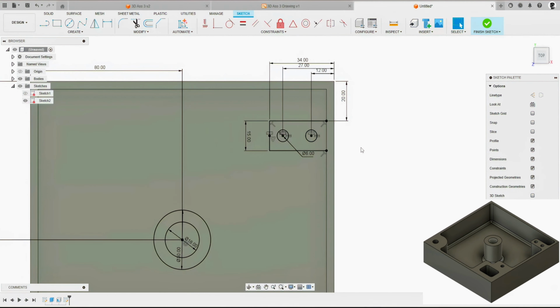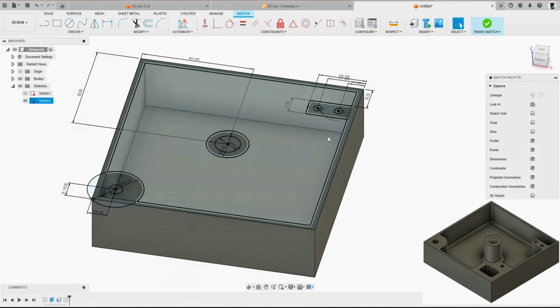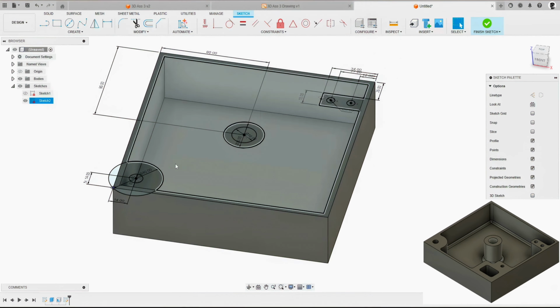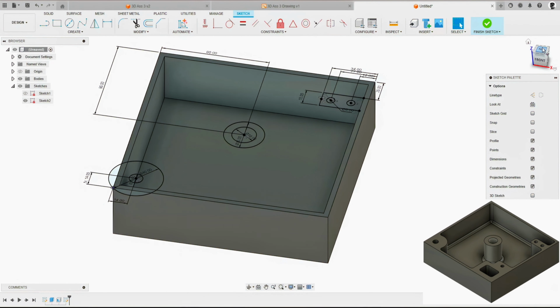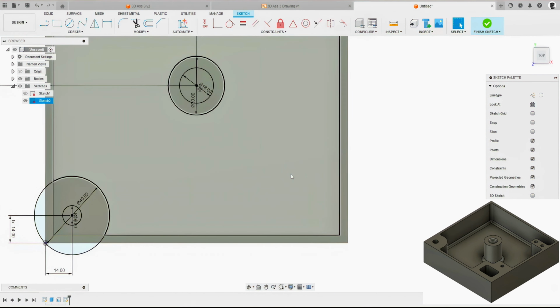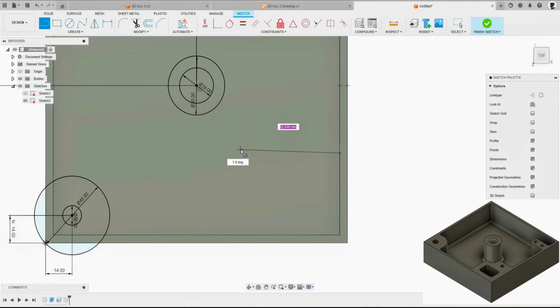We've got our profile to extrude there. I'm drawing on the top plane. As we can see, we've got our 1 profile, 2 profile, and 3 profiles ready to extrude down to this face here. And so the last feature to add is the slightly complex one down in this corner. Let me go ahead and use the line tool and roughly draw in this geometry. I'm going across, down, across, and down. And then trim this up.